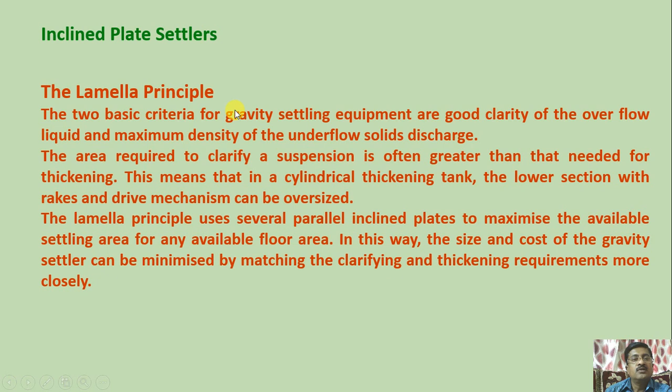Now again we'll proceed further. Instead of tube settlers, inclined plate settlers are also there. Generally the lamella principle is used. Now what is the lamella principle, that we'll see. The two basic criteria for gravity settling equipment are good clarity of overflow liquid and maximum density of underflow solid discharge.